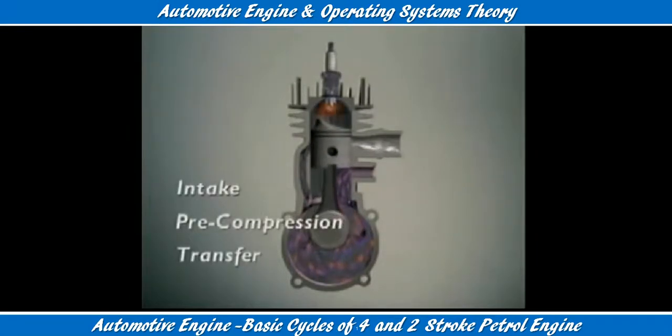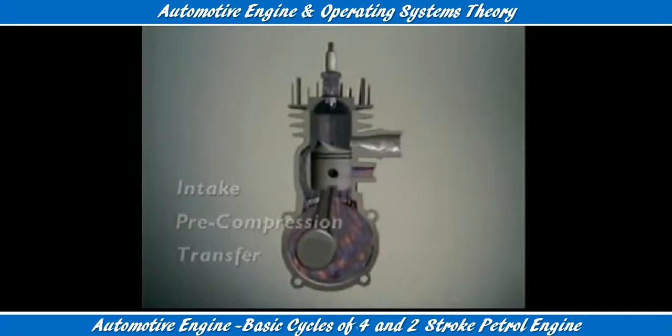Notice the events that occur below the piston. Intake into the crankcase, pre-compression of the air-fuel mixture in the crankcase, and the transfer of mixture from the crankcase through the transfer port and into the combustion chamber.